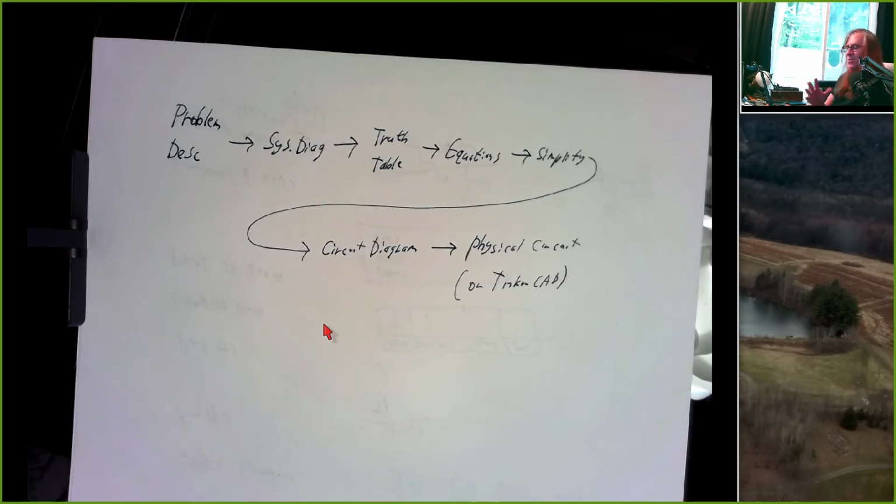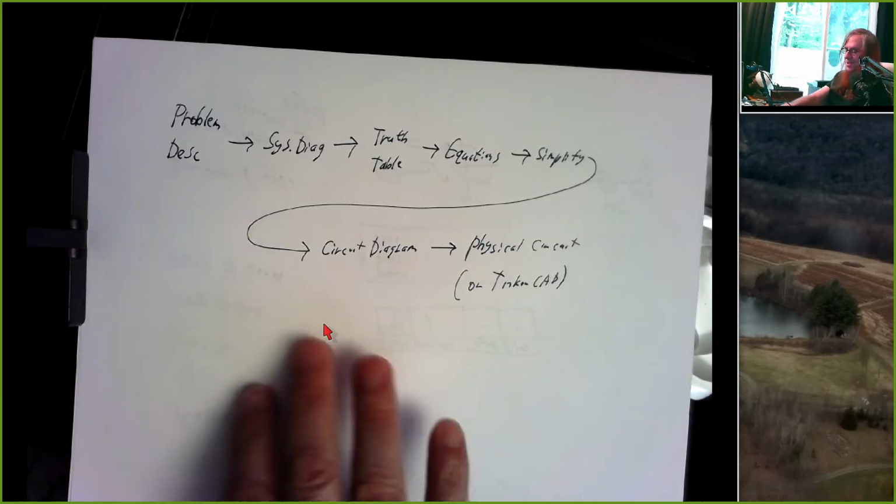But sometimes you might want to wire things differently. It might take fewer parts if you wire it up so that the LED turns on when the output feeding into it is a logic 0. So you're going to switch your LED around into that third configuration. Well, that's got to be in your circuit diagram.